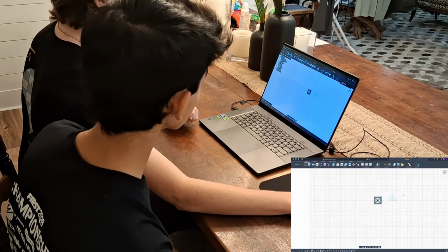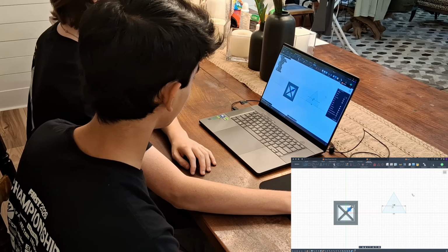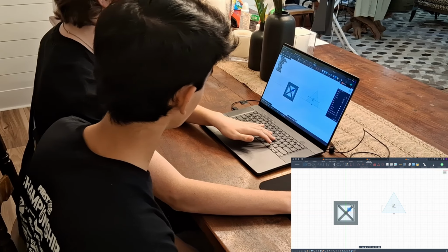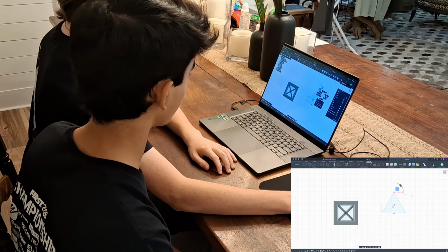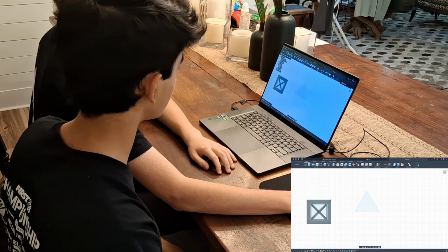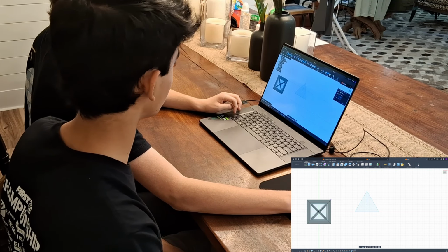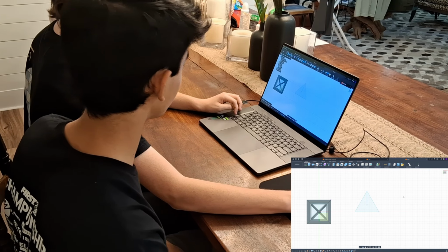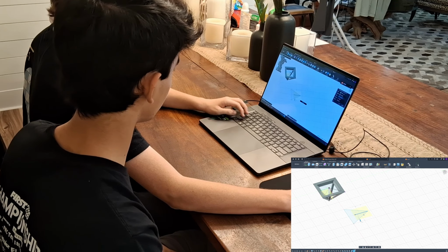So, make the line. Make sure you start with your sketch again. That's good. And then line up to the vertex. Okay. Now you're gonna do your plane at the angle. So finish your sketch, and find your plane at angle. There you go. Now make sure you click that edge and go up 90 degrees.